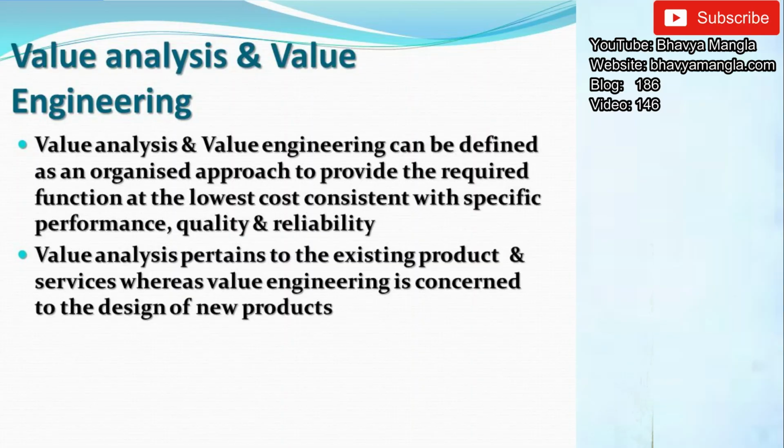So in short, value analysis is primarily when the product is in the manufacturing stage after development, and we need to see what reduction we can do, keeping the cost and the quality the same. When we talk about value engineering, the intent is that during the development stage, we look at what we can do in the product and process so that we can optimize the cost and give the best value to the customer.